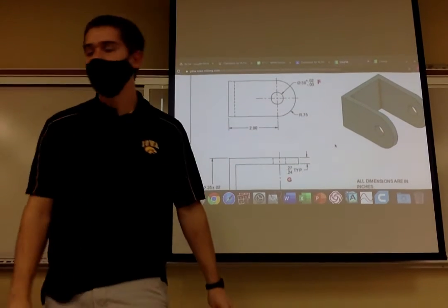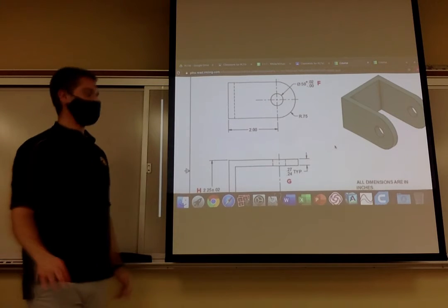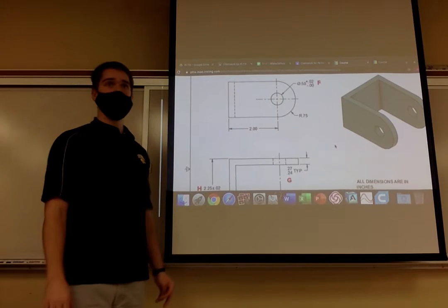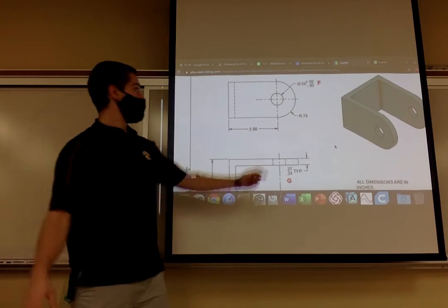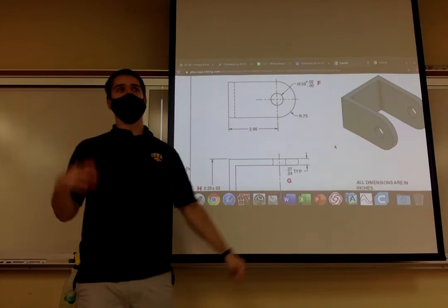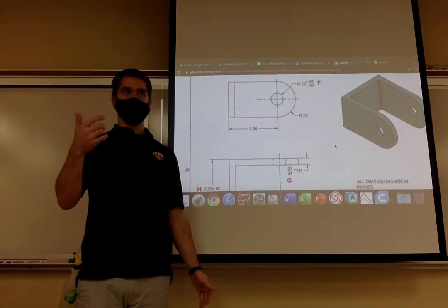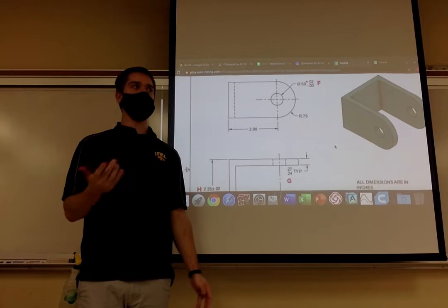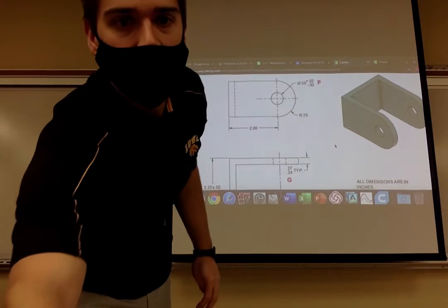Really quickly, looking at another part, what's F? What type of dimension or tolerance? Unilateral. You only give room for error in one direction. Unilateral. Total tolerance? 0.02. The total room for error is only one direction, so that's it.